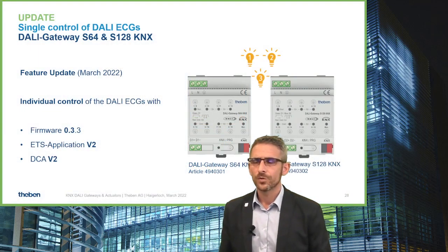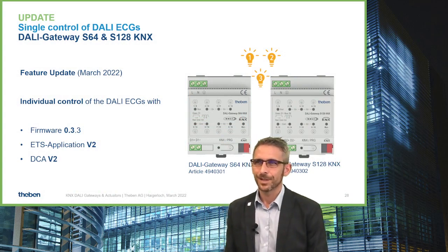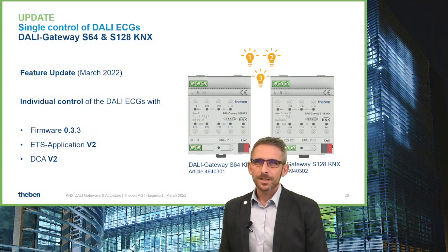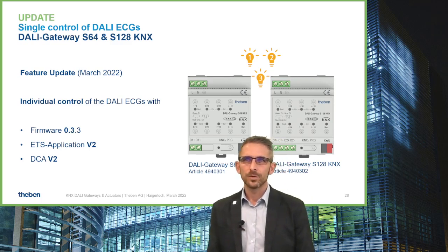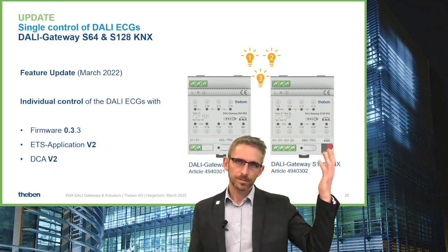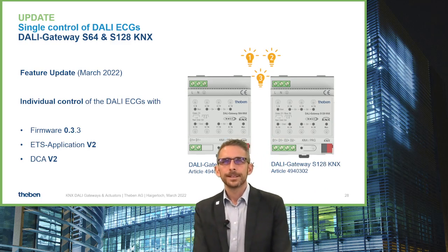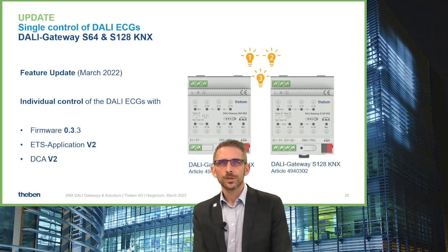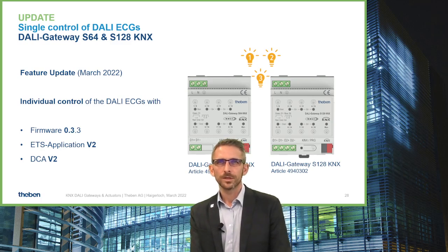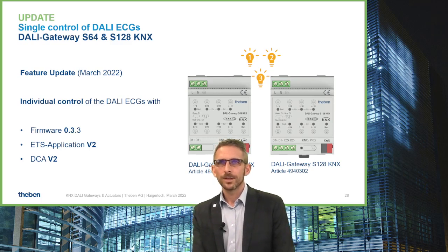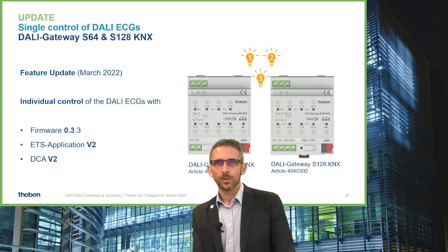And we have some news regarding these DALI gateways, because in the past we have had the possibility to control with each DALI gateway up to 64, or with the 2-channel 2x64 DALI control gears in groups. But there has not been the possibility to control the DALI control gears individually. And now we have an update available.